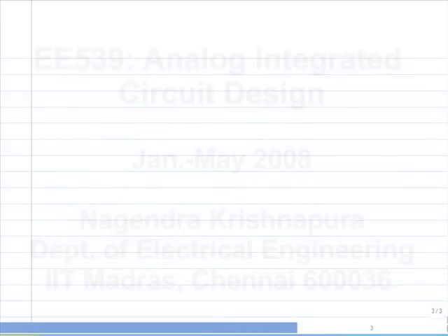So we have seen that with the feedback system, we can control the output to be some function of the input. For our case, we are concerned with linear functions, that is, trying to make amplifiers, but it doesn't have to be. It can be some nonlinearity also. Now, to do that, we need an integrator, but we can't make an exact integrator. We will have a finite DC gain, that is the non-ideality on the low frequency side. And also, the response will not be minus 20 dB per decade at very high frequencies. It will have a higher slope because of parasitic poles.